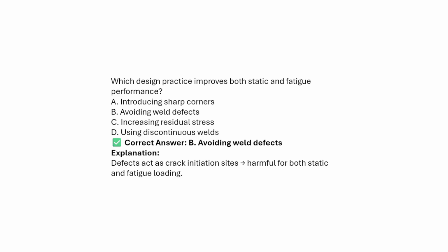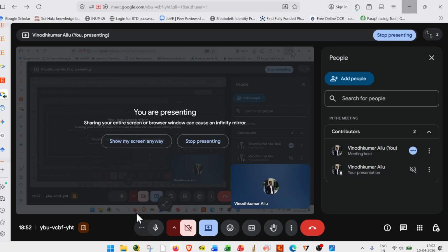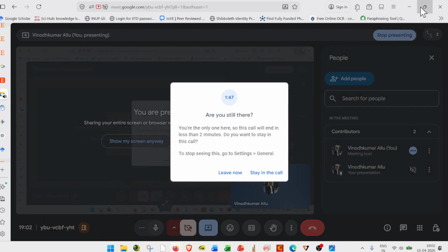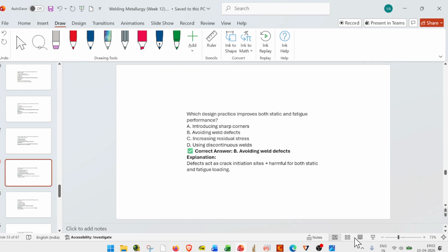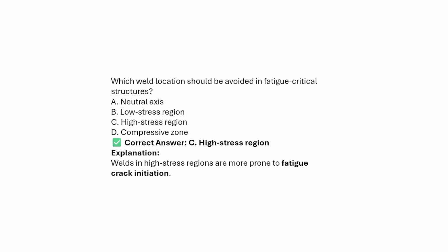So the correct answer will be avoiding the weld defects. Defects act as crack initiation sites that are harmful for both static and fatigue loading.